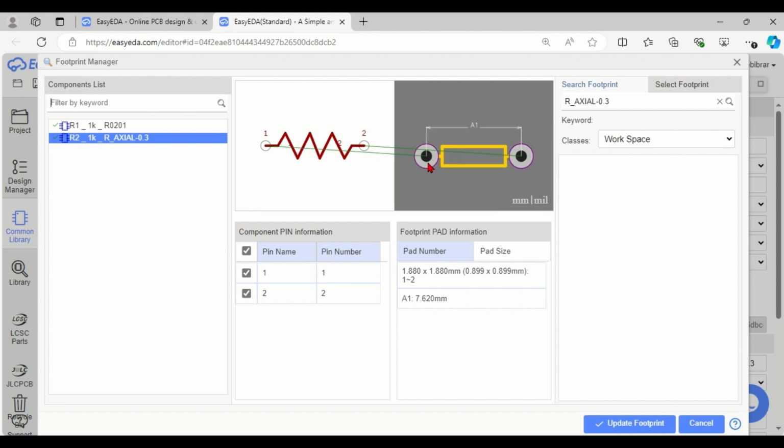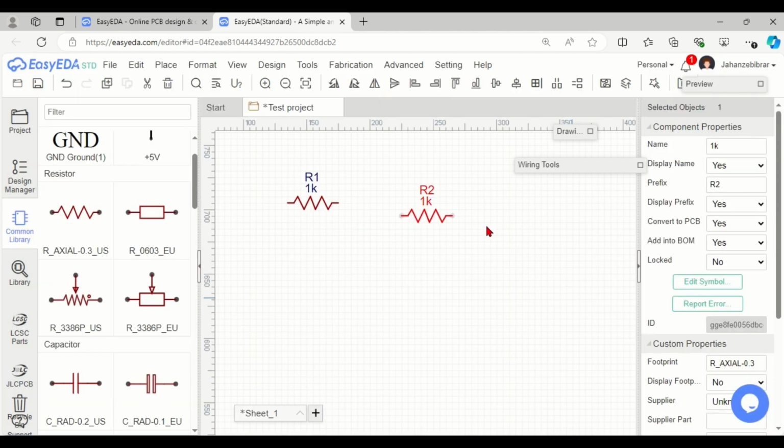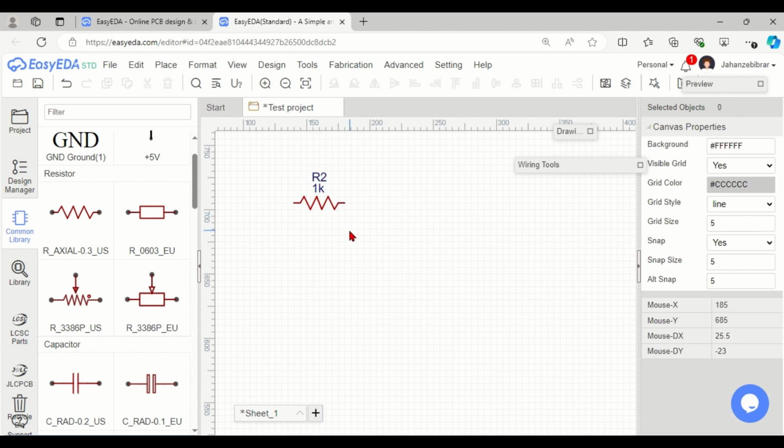It shows that I have multi-layer pads with holes in them, and the component outline looks similar to the one I have for my resistor. It's approximately 7.5 millimeters long, which is more than enough for the resistors I have in my lab. So that's great. I'm going to use this part instead because it's a through hole component.